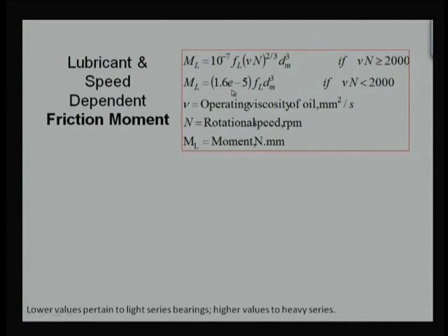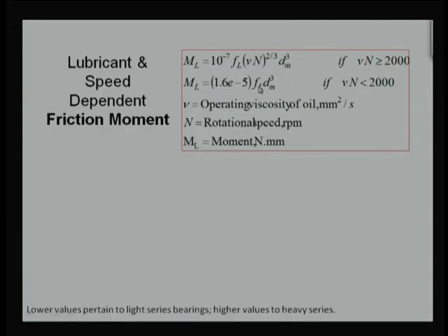It's not going to change with the speed or the viscosity. By and large the value is constant, except that it depends on the f_L parameter, which again depends on the bearing type or geometry, the lubrication mechanism, as well as the bearing geometry.